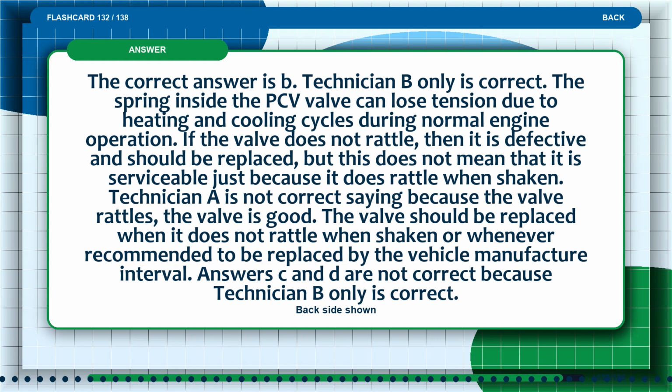The correct answer is B. Technician B only is correct. The spring inside the PCV valve can lose tension due to heating and cooling cycles during normal engine operation. If the valve does not rattle, then it is defective and should be replaced, but this does not mean that it is serviceable just because it does rattle when shaken.